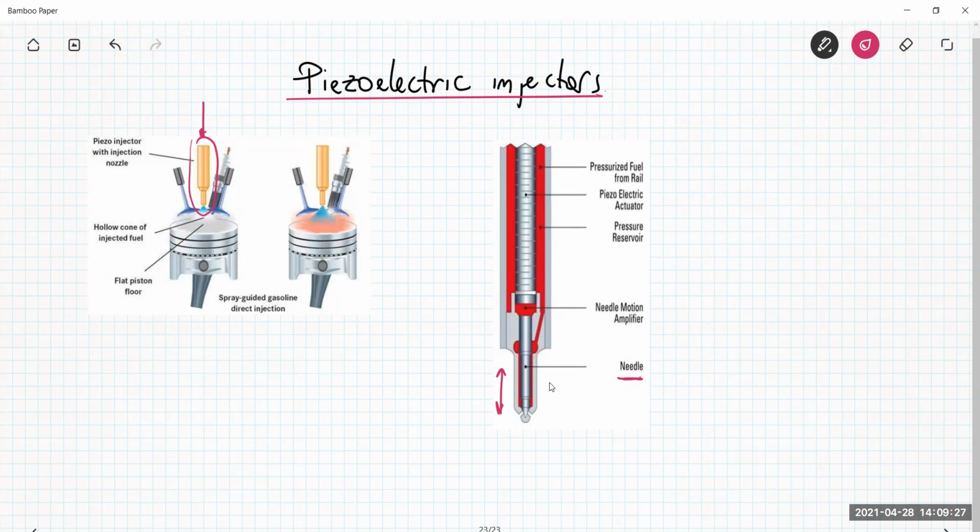Typically, this kind of behavior, rising up and down this needle, is performed by using solenoid injectors. There are typically two classes. One is the solenoid injectors. The solenoid injectors are based on the presence of coils. In these coils you can make current flow, making possible a specific mechanical action in the injectors to move this needle up and down.